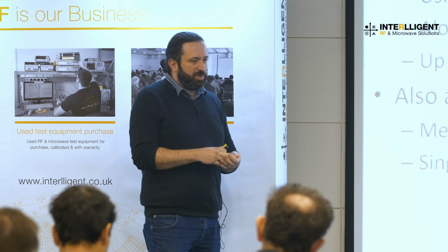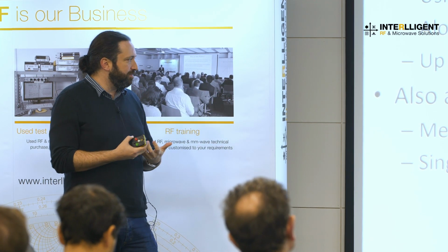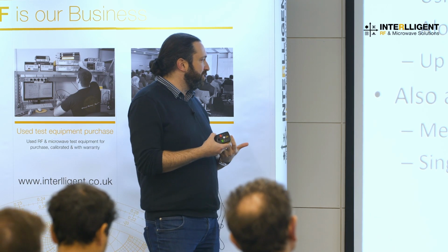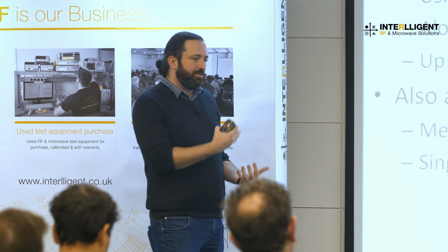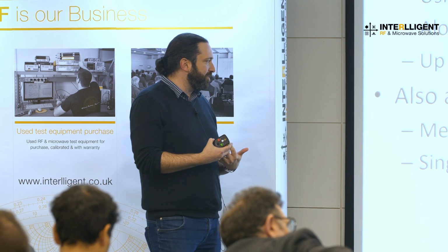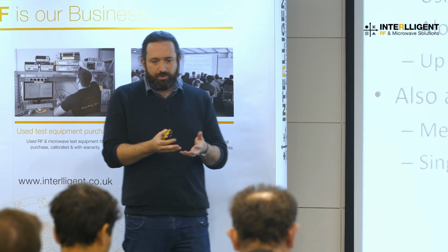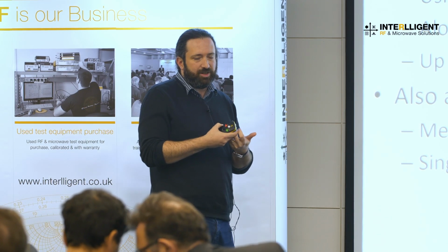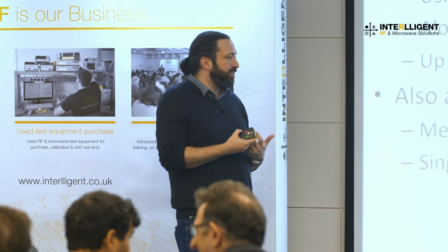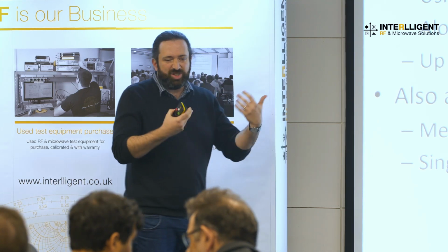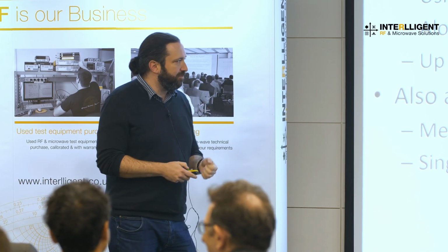But more recently, there's been a lot of development for 3.5 gigahertz for MIMO systems, TDD type systems, where the power is a bit lower. So we start to see some of the things that happen a lot at higher frequency. For example, a lot of the solutions you can buy now are single package Dohertys, where they integrate most or all of the matching and combiner, and they also integrate drivers. So it's becoming similar to what happens at high frequency.